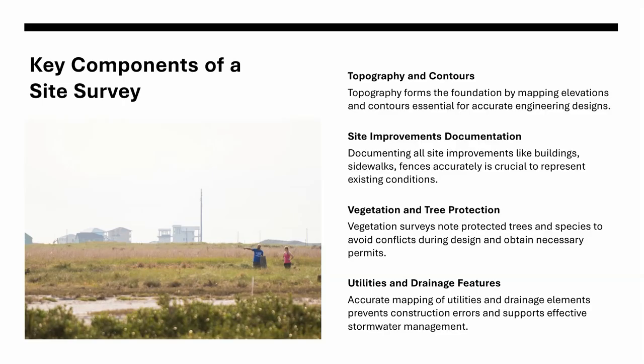Topography is often the backbone. Field crews will take shots across the property, locating elevations at key points. Break lines are gathered at ridges, swales, curbs, and ditches. Those points, once imported into Civil 3D, form a surface, and from that surface, contours are drawn.